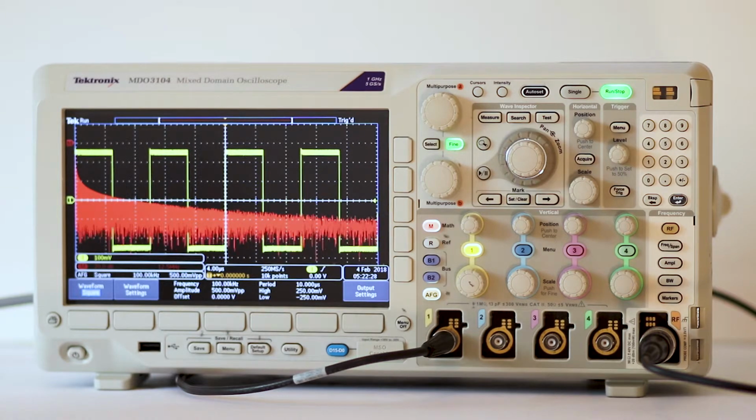These very fast rise and fall times are in essence high-frequency components which generate large amplitude harmonics visible in the frequency domain. Notice that they diminish in amplitude farther in frequency from the fundamental until they are lost below the noise floor.